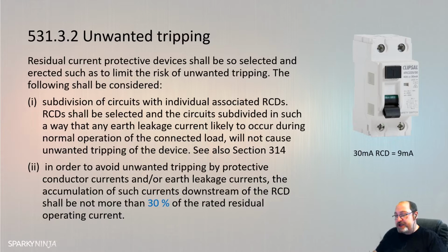They're saying that we need to make sure that when we install an RCD for a circuit, to verify that it does not start nuisance tripping due to, again, cumulative protective conductor currents or maybe some earth leakage, we've got to verify that the amount of equipment being plugged into it does not give off all this protective conductor current that will result in this thing nuisance tripping. So again, it's more information that we probably should seek at the design stage if we can.